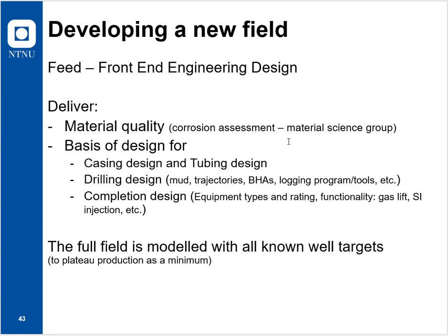We will have to acquire pressures and the composition of the fluids to be produced, and rates, so that we understand approximately the phases that will be existing in the well construction. Will it be gas? Will it be liquid only, or so on, and any scaling potential, and so on and so forth. We need to understand.